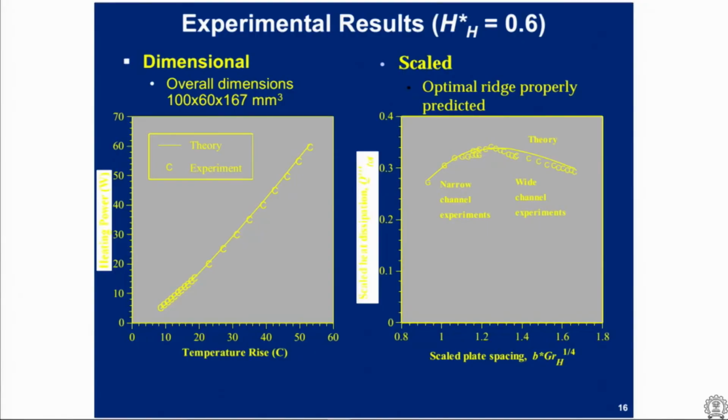Otherwise, increasing surface area in natural convection always has the countering problem of increased frictional losses that reduce velocities. So, we cannot simply increase the surface area; one has to increase the velocity, and that is always obtained by using chimney-type situations. That is an example of chimney-enhanced natural convection in heat sinks.